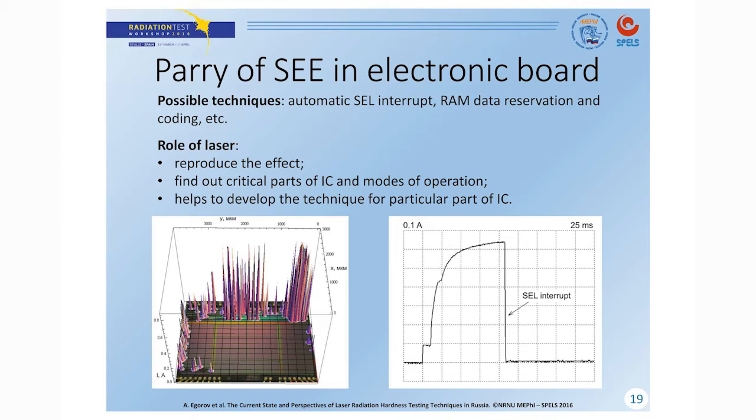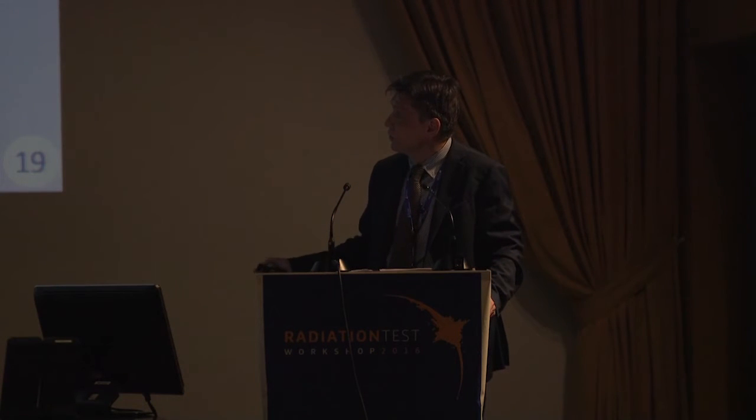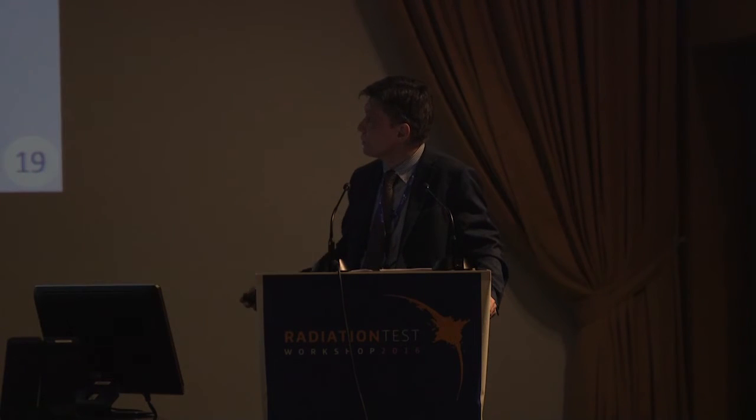One of them is the SEE hardening technique. Here the laser allows us to reveal the critical modes of operation and to develop and improve these techniques selectively for different regions of the IC, and to develop the hardening methods of single event latchup, for example.